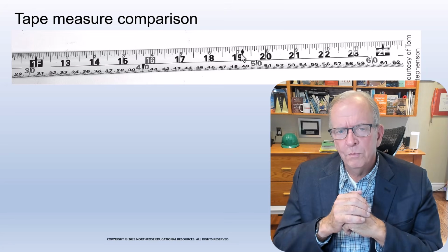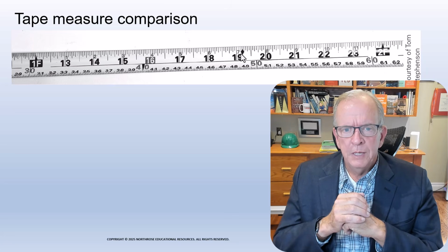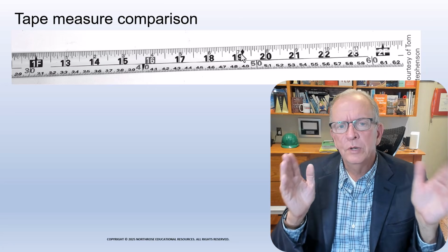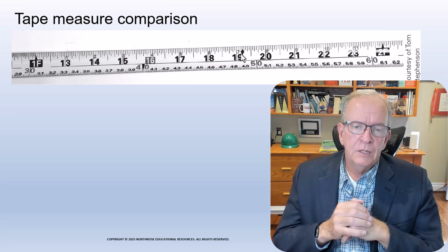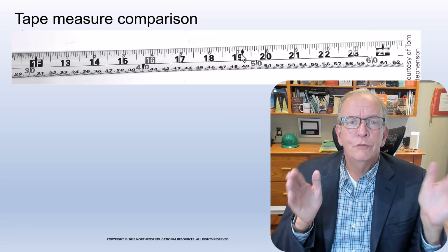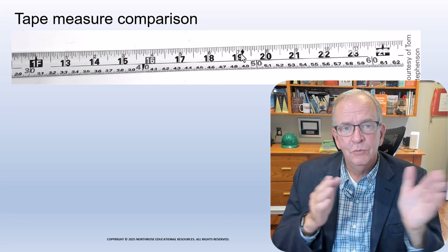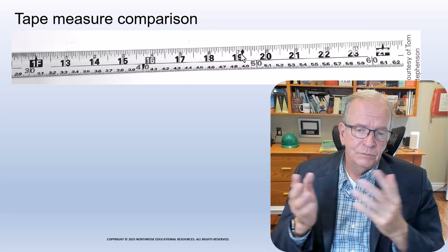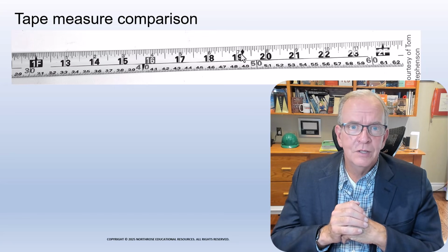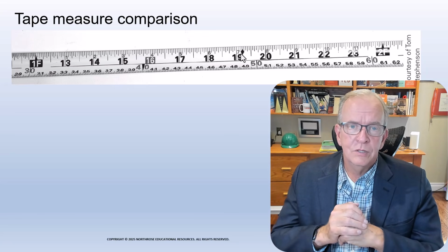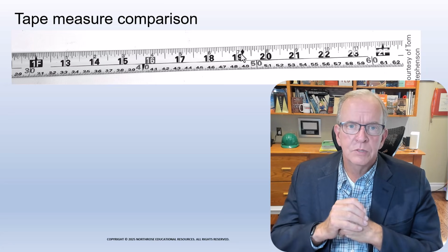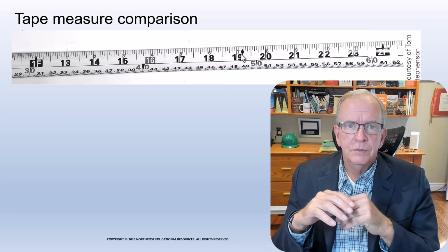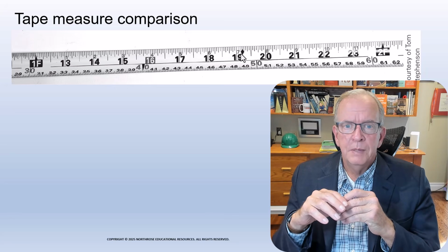One of the big home builders that I used to do a lot of consulting work with, Mattamy Homes, at one point they were doing a lot of houses, I'm not sure if they still are, at 19.2 on-center stud spacing. And the logic there with 19.2 is we will use fewer studs on a home. I don't know, if it's 50 studs on a home less, and each one's $6, that's $300 in a home. That's a nice little savings. May not seem like that much, but if you build 6,000 or 7,000 homes a year, it makes a difference.